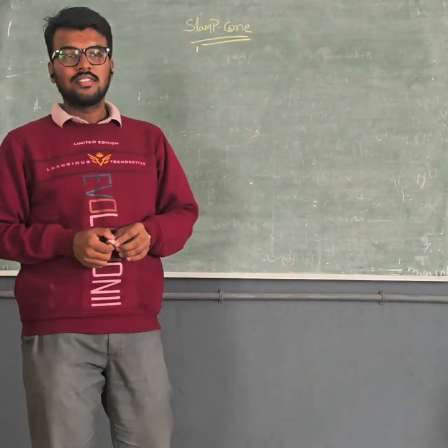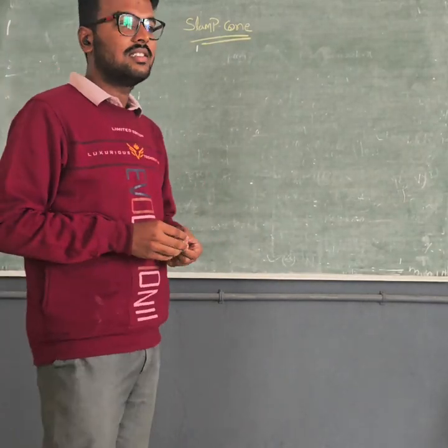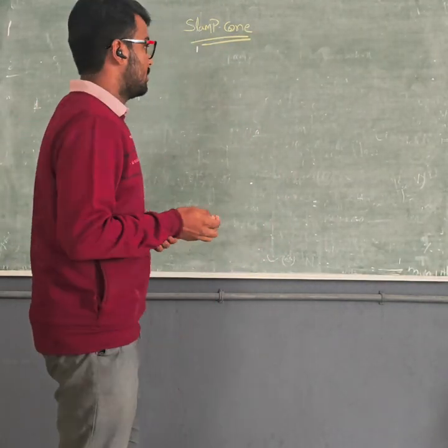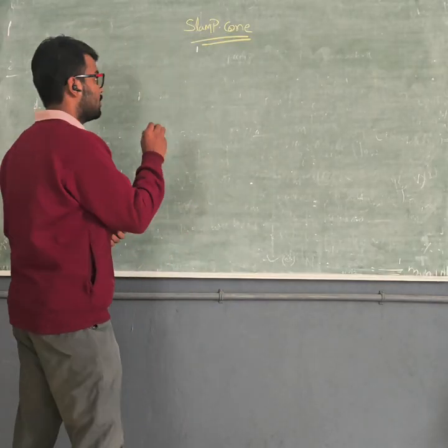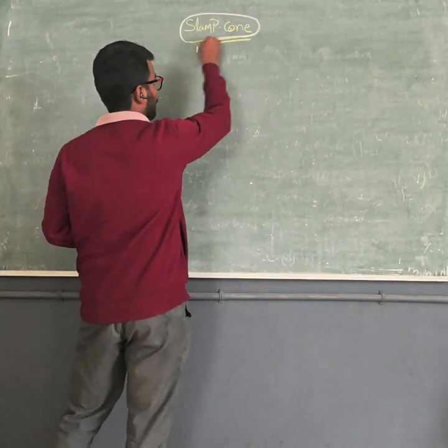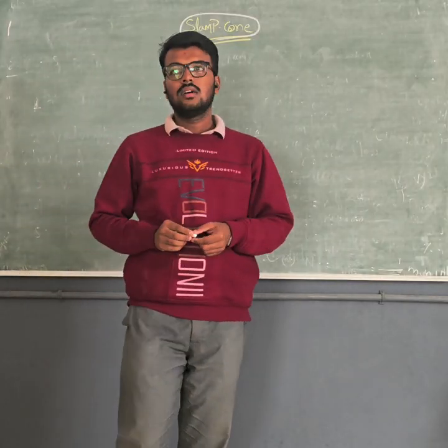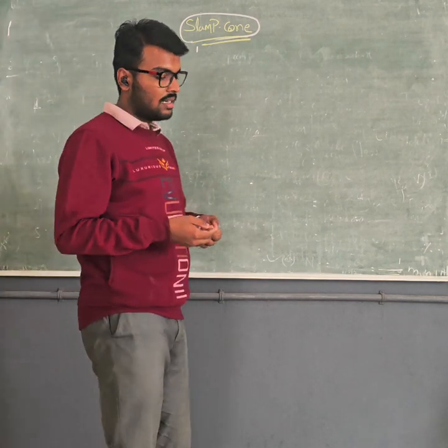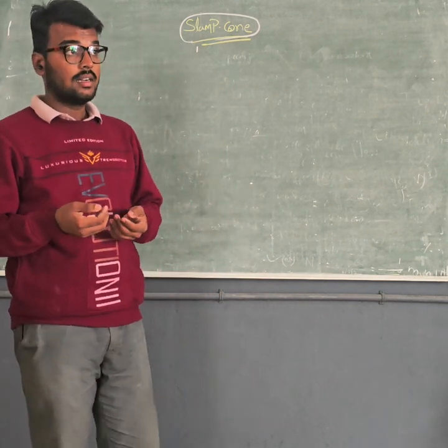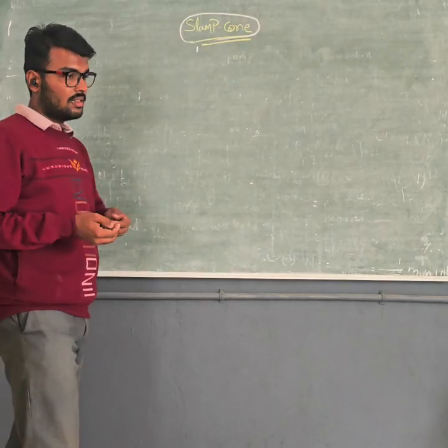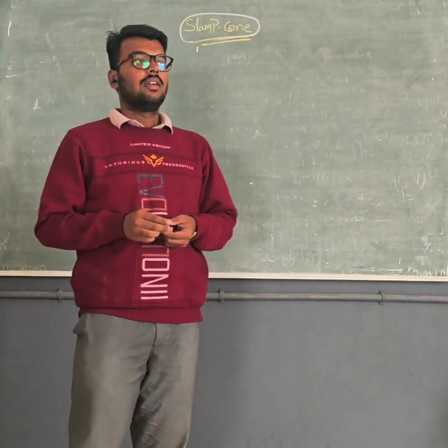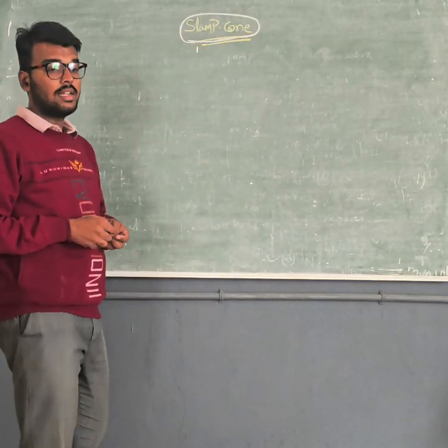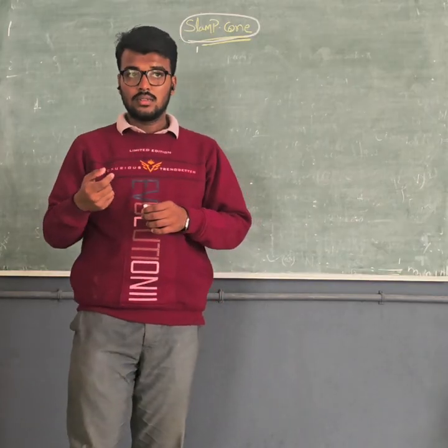So we are going to discuss the slump cone test, which is a part of building material and concrete technology. Let's understand what is slump and what is cone. As you know, at various kinds of sites we test concrete before casting. We test whether the concrete is applicable for our site or not. Slump cone is one of the tests where we check the consistency of the concrete.